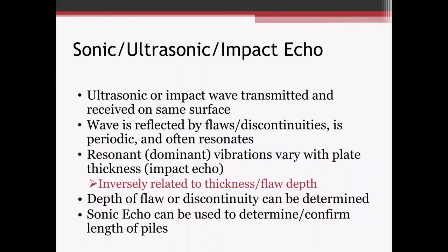So we'll start talking about sonic, ultrasonic, and impact echo. All of these are the echo methods. Basically, you have a wave that's transmitted and received on the same surface, so you don't have to have access to both sides. This is good on maybe a slab on grade or a spillway. Whatever wave you put into the concrete is going to get reflected by any flaws or discontinuities.